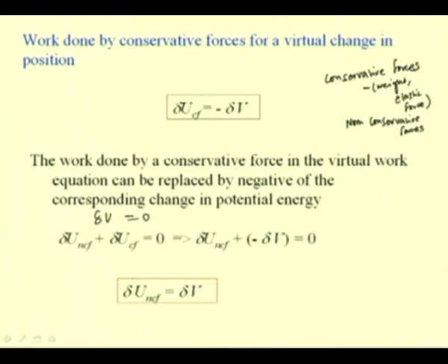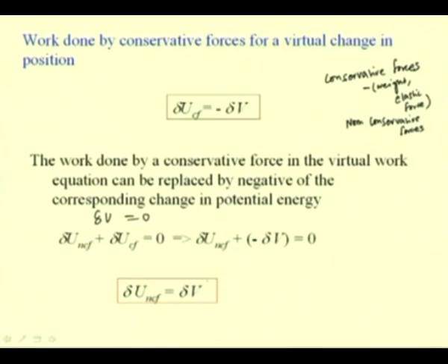So, the equation of equilibrium by the method of virtual work can be replaced by this equation, where we equate the work done by the non-conservative forces to the change in the potential energy of the system. We can solve equilibrium problems by using this equation, where we can avoid the weight and the elastic force in the active force diagram, and one can compute the equilibrium.